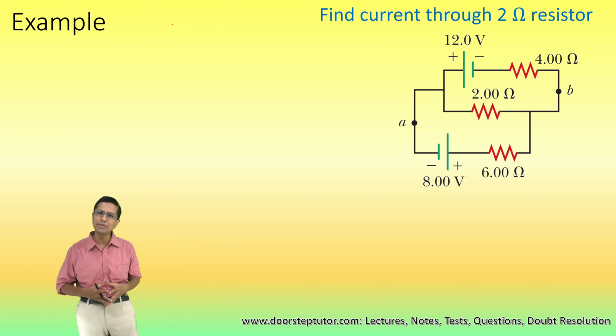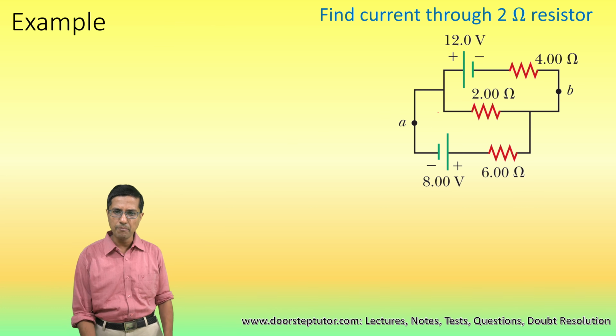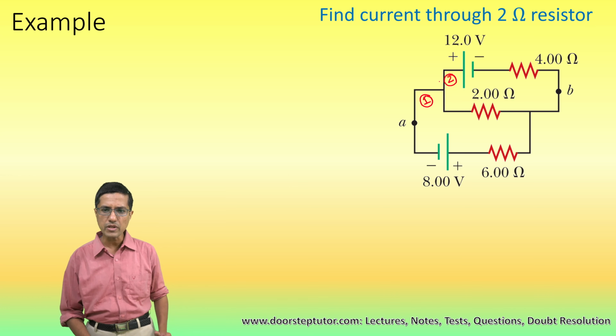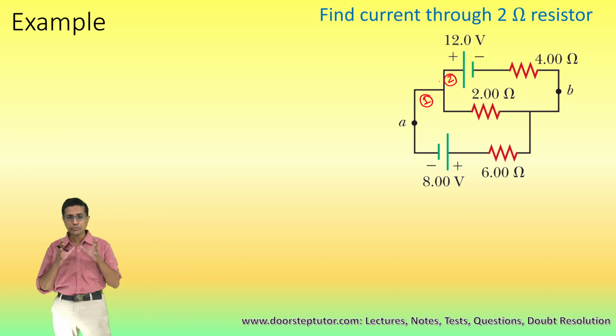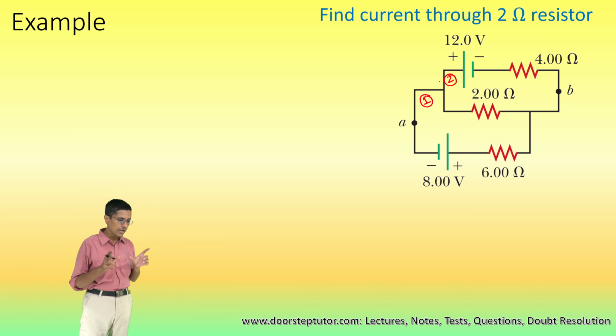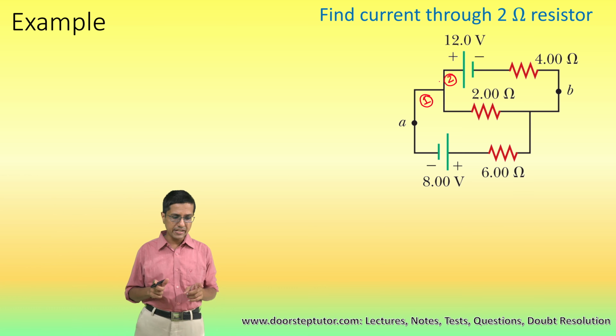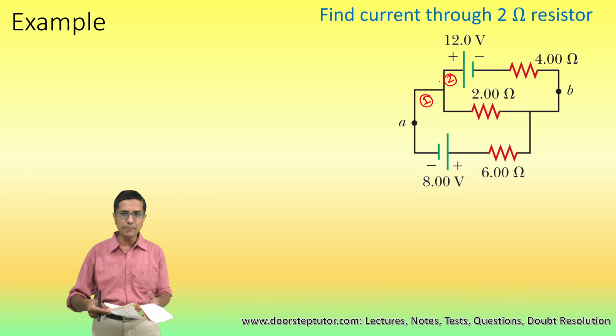So what are meshes? Meshes are not a difficult concept. Meshes are the loops inside the circuit which cannot be broken down into any smaller loops. So the first thing that we need to know about when applying the mesh analysis is that it can only be applied to circuits which can be put in a plane.